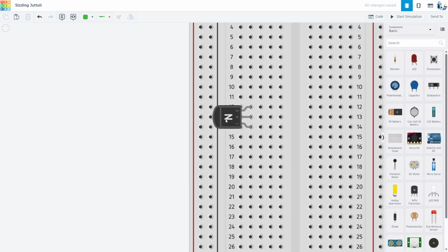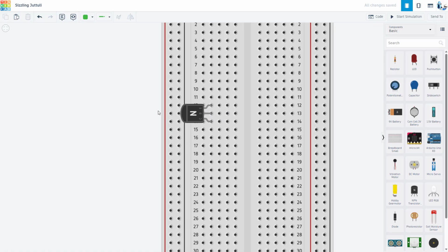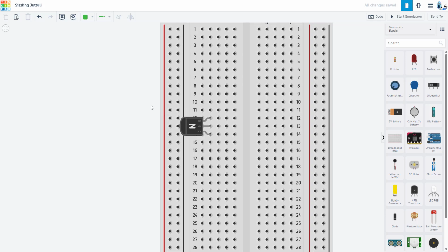And our goal, we're not doing a microcontroller or anything in this video, is just to connect a load, so I'm going to put an LED with a current limiting resistor and a base resistor separately so we can measure the current into the base and into the collector, and we can see the relationship between those two quantities.